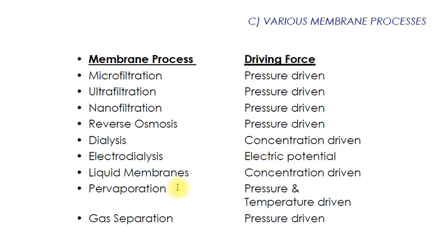In liquid membranes, the driving force is concentration. In pervaporation, the driving force is pressure and temperature. And in gas separation, the driving force is pressure. I have already discussed most of these processes in this course, and during the explanation I also mentioned the driving force. So these are the driving forces.